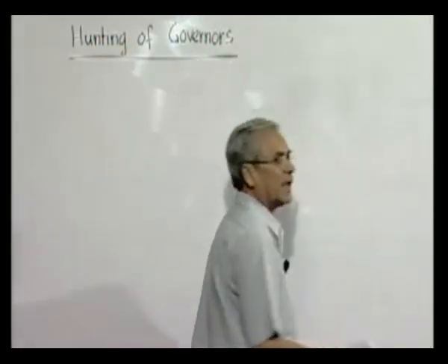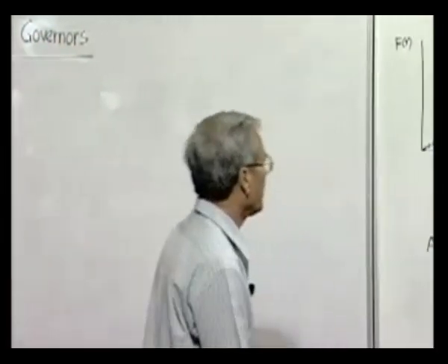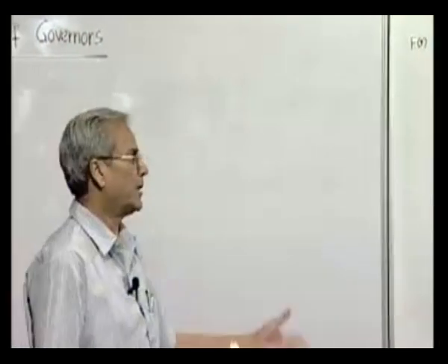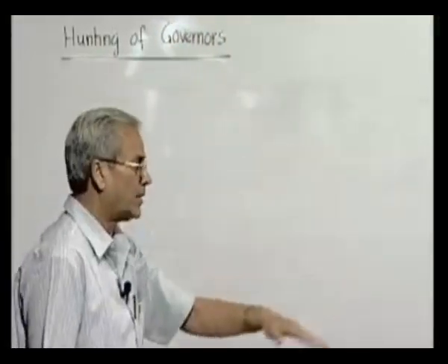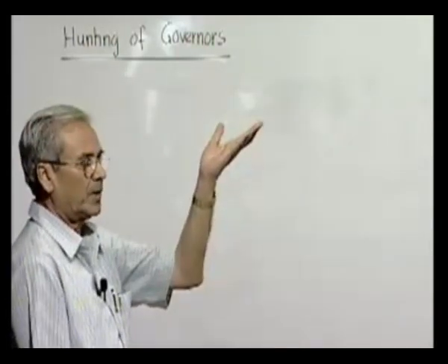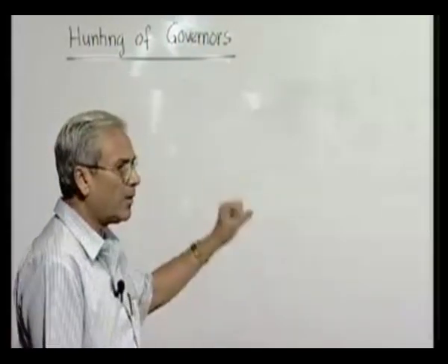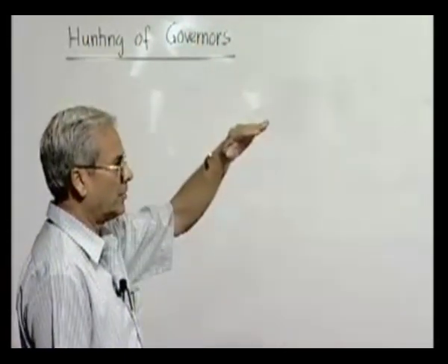Now we have seen how a governor functions. When a system is running, suddenly due to some reason, maybe a change in the load or change in the input, maybe the load is less. So governor will try to speed up, and as it does, we are controlling, cutting down its input. So therefore then it will again start coming down to the required level of speed.